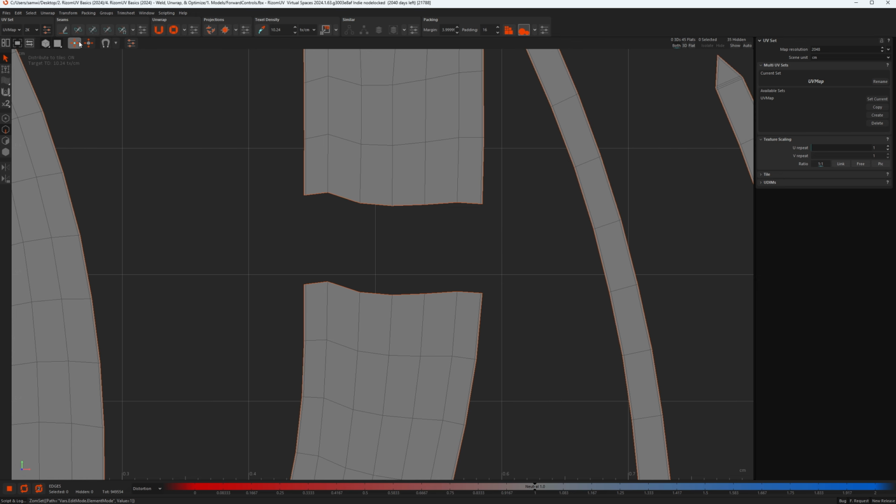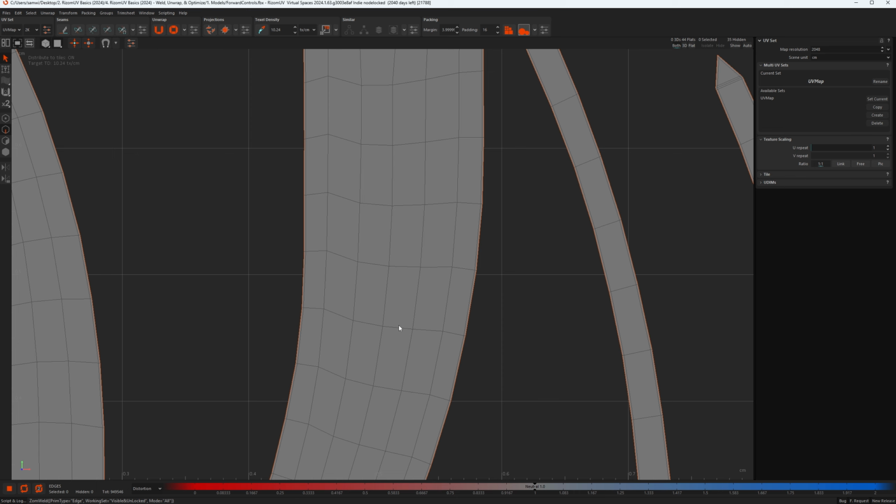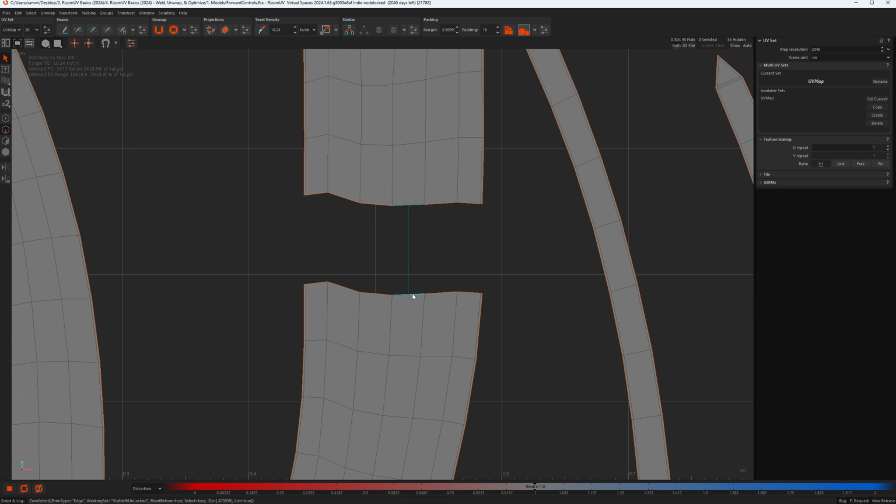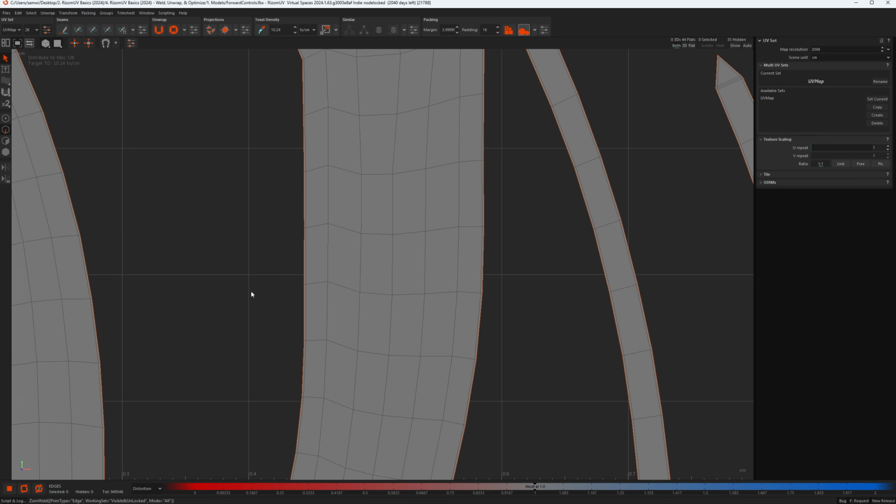So first we're going to be looking at the Weld Tool, which is here, and its shortcut is W. And to demonstrate this, I'm going to select this edge here, double click for a loop selection, and I'm just going to press the shortcut for Weld, W. You'll notice that our counterpart island at the bottom here was moved upwards to our selection, and then a weld occurred.